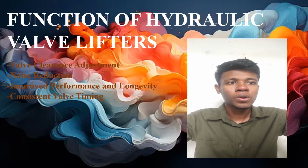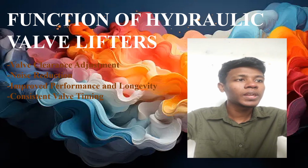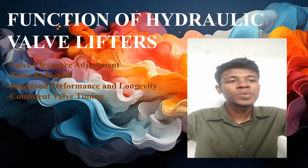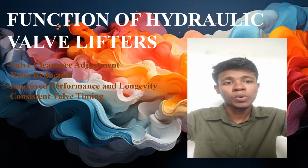The functions of a hydraulic valve lifter. The first one is valve clearance adjustment. The main function of a hydraulic valve lifter is to automatically adjust the clearance or gap between the engine's camshaft and the valve train components, such as the pushrod or rocker arm. The adjustment compensates for any wear or thermal expansion in the engine components and ensures that the valve closes properly.